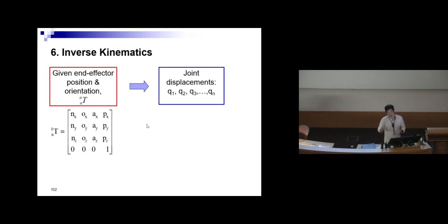So for your assignment, you are going to draw the letter, for example, the letter O. You may need to have some sample points, and then you use the inverse kinematics to determine the joint values. The transformation matrix can be represented in this manner. You have nx, ny, nz, ox, oy, oz, ax, ay, az defining the rotation matrix, and then px, py, pz being the translation vector. In our context, the scale factor is always 1.